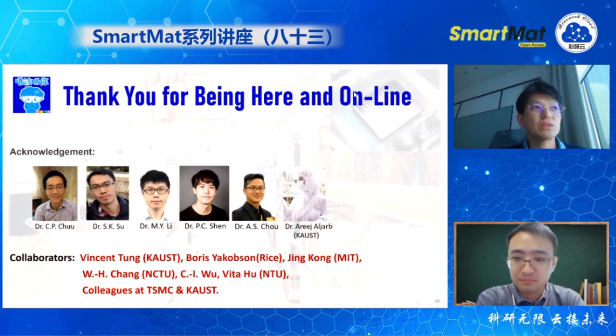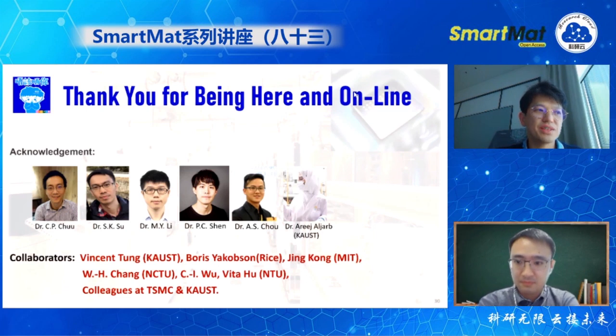So the 1D carbon nanotube is also a very excellent choice, because it is one-dimensional and has a very thin diameter. And in terms of performance, I think a 1D channel like CNT should perform much better than 2D. That's for sure.